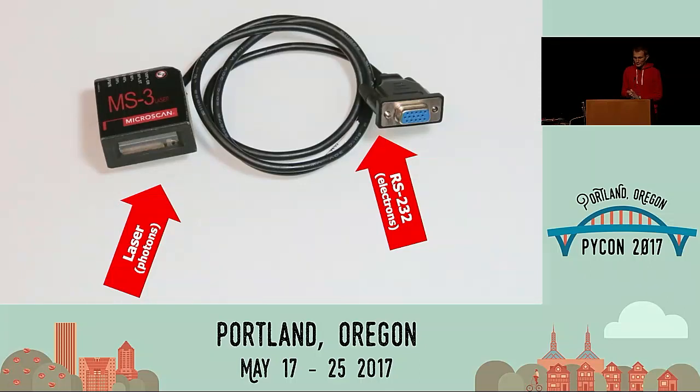And it's using this protocol called RS-232. Some people in this room might be too young to remember computers having serial ports. RS-232 is what specifies the type of cable, how long, how many strands, all that kind of stuff. Also the type of data going through it. The good news is Python is old enough to remember the serial port. So there's a library to talk to the serial port in Python.